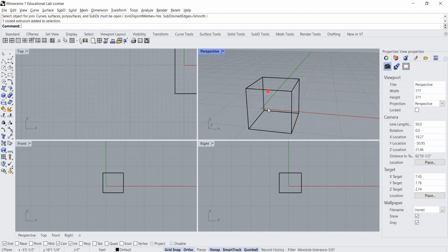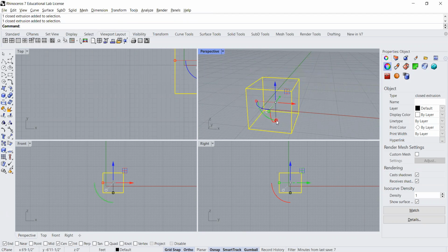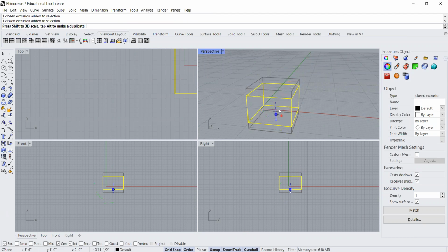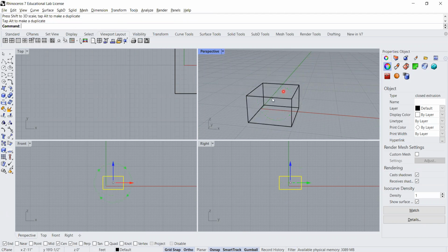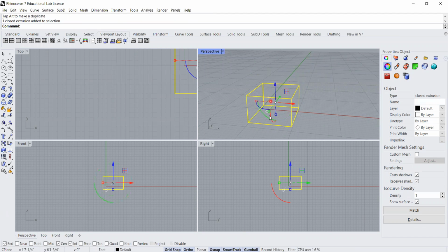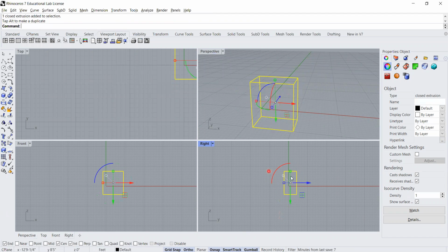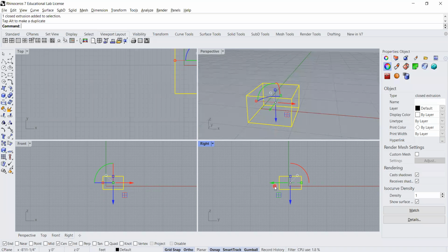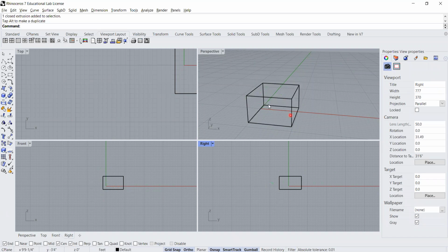The Gumball also has other things that you can kind of manipulate with it. You can sort of stretch things and rotate them. So, you may want to just kind of bring in a 3D form and just kind of play around with what it can do, right? So, yeah, that was a rotate process there. You could give it a dimension or an angle to rotate, that sort of stuff. So again, that's the Gumball, and that can be a really useful thing to turn on.